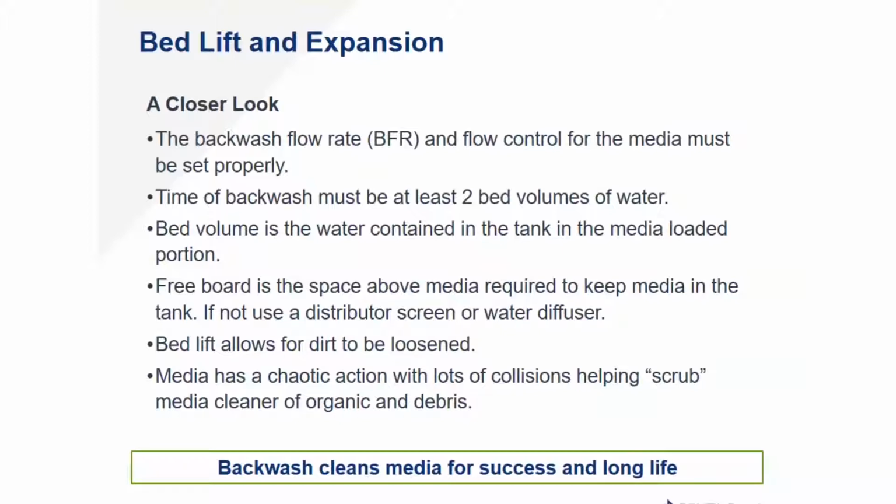Too little, we flush the media out of the tank. Freeboard is the space above the media required to keep the media in the tank, but yet allow for proper backwash. If not, you want to use a distributor screen or a water diffuser to retain that resin. But if you don't have enough room for that bed expansion by the media's OEM requirements, you aren't going to get a good backwash, and your media life and capacities will suffer, especially longer term.